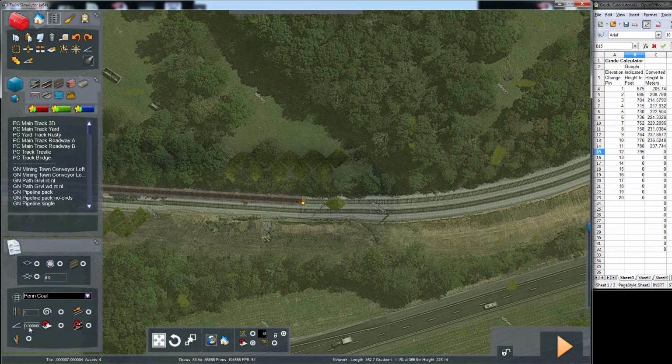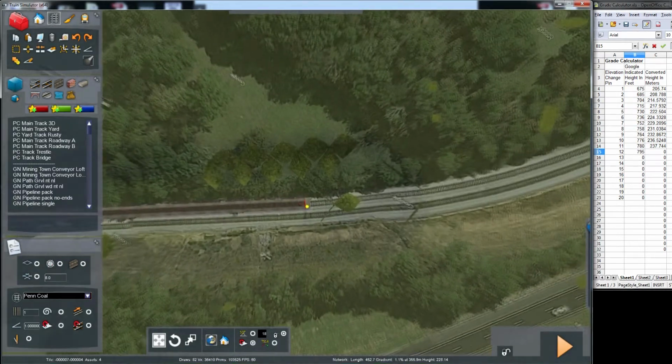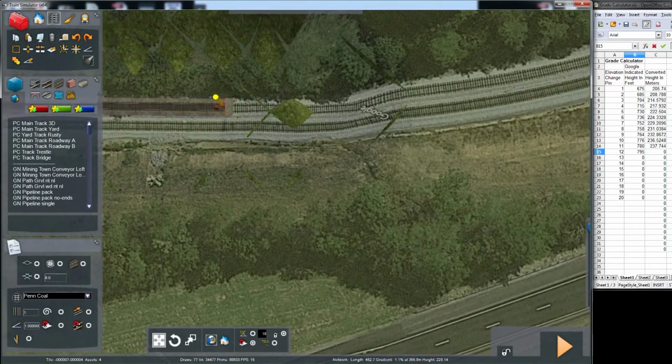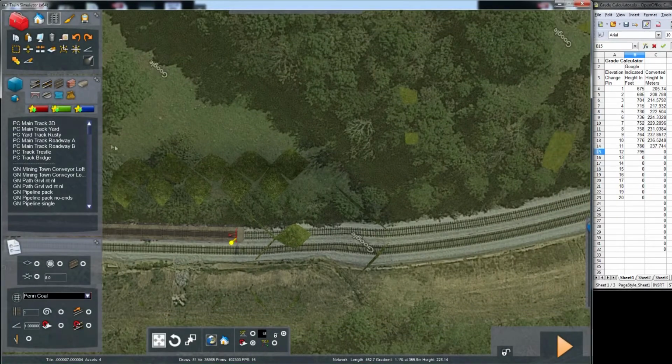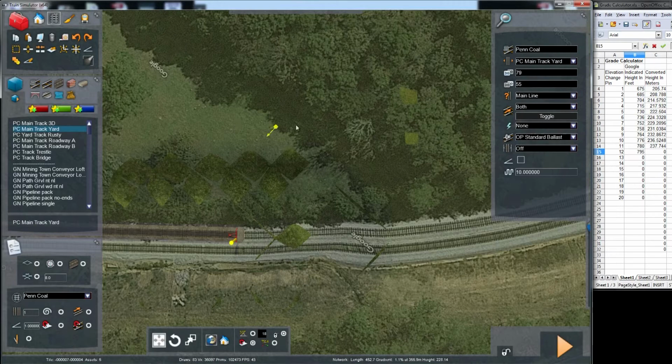Actually, I'm going to change that back to about, let's make it 1 inch of 1%, excuse me, 1 foot in 100 feet. And let's leave that on the incline like that, because we know we're climbing here. There's no doubt about it. All of our measurements that we've made indicate that we're climbing. So adding some grade into that just eliminates some of the down that you have to take.